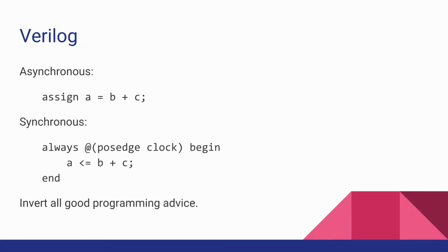So you can imagine, in a programming language, let's say you have a function. You pass in a parameter, the function does its thing, and it gives you back your answer, and then you have your answer. The equivalent in Verilog is you've got a function, and you pass it the address of your parameters, and the address of where you want the answer to go. And it starts a thread to compute that, and then returns immediately. And at any time in the future, you can change your input variables and it'll magically figure out the answer and stick the answer into the thing, at any time. So you're looking at a variable, you have no idea how is this going to get changed and when?